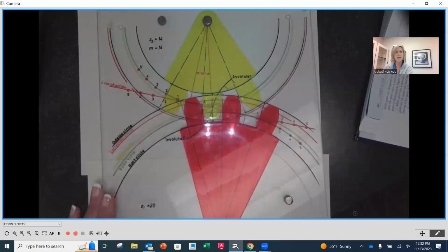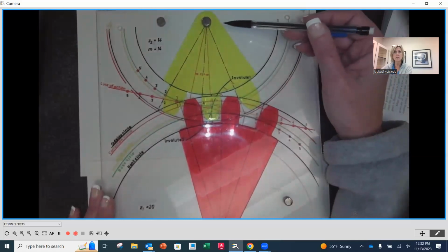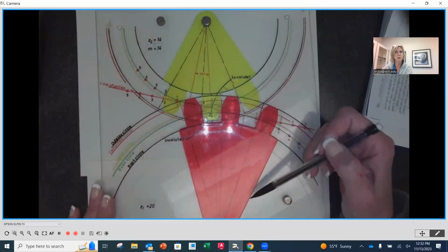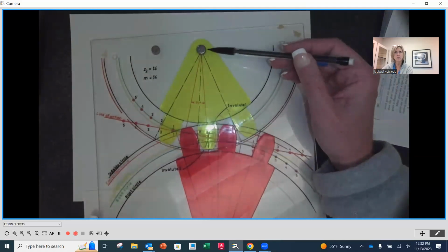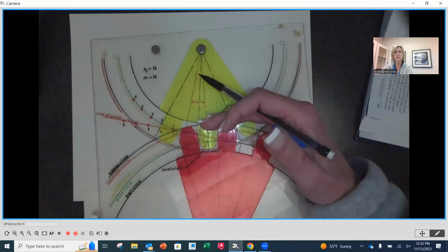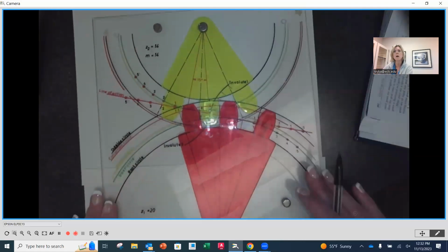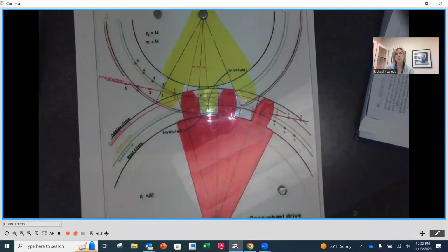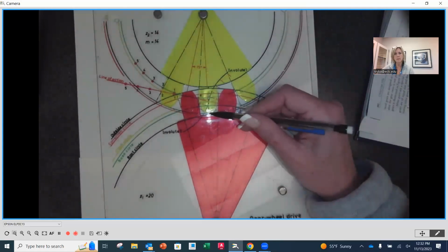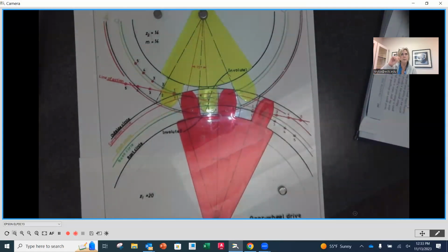It also means that we have to mount these correctly on the correct centers. If this is off by too much, it's going to push that gear down or too far up, and then we could have problems. So when we're mounting gears or determining the center distances, we have to be aware that we've got a clearance we can work within, but we can't exceed that or have those teeth bottoming out. As the designer, you have that responsibility. Just keep that in mind.